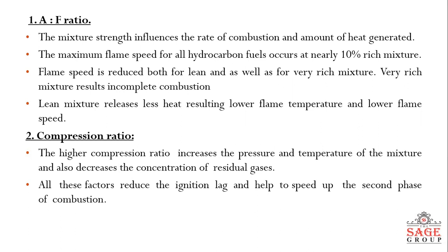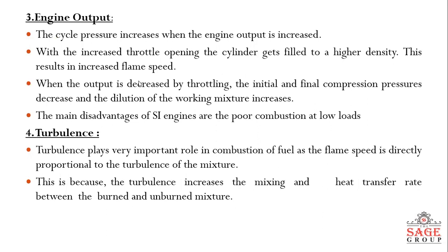This increases the peak pressure and temperature, and the total combustion duration is reduced. Thus, engines having higher compression ratio have higher flame speed or lesser combustion timing. Then, engine output. The cycle pressure generally increases when the engine output is increased.